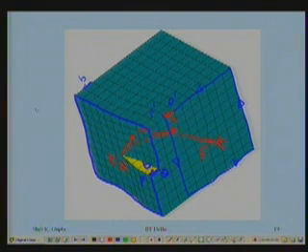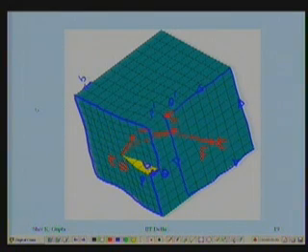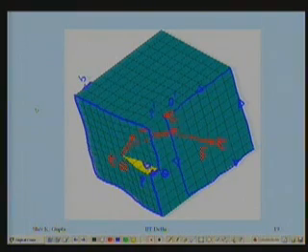That's why whatever may be the shape of the boundary between the slipped part and the unslipped part, this slip vector by which one part has slipped with respect to the other in the crystal is the same. Everywhere it is the same, it is not changing. T vector of course is changing, because that's a tangent to a dislocation line, and dislocation line need not be a straight line. Therefore, this tangent will keep changing. Is that clear? We shall start from here in the next class.